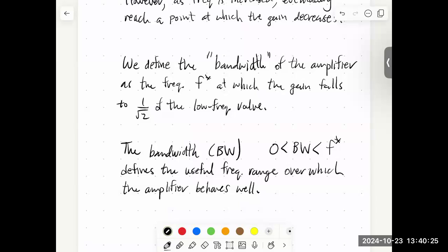Yeah, you do have some flexibility there. If I use a really small resistor for R1, then you're going to get pretty large currents going through your circuit, and maybe you want to avoid that. So bigger resistors just make smaller currents, less power dissipation. Yeah. Okay, so we have 10 minutes left.